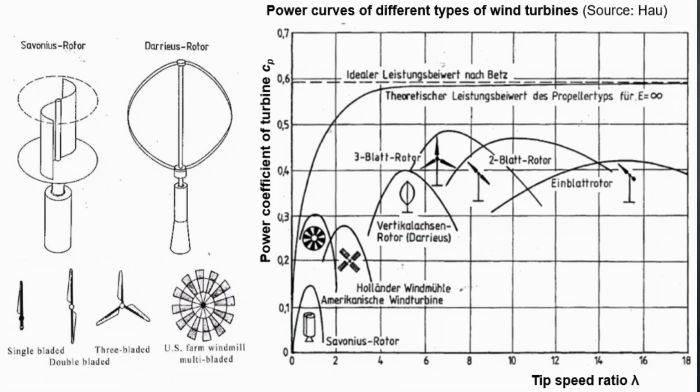Here, there's also a publication, German, so you see here the highest is the single blade rotor with a tip speed ratio, but you don't see those wind generators very often, or let's say extremely seldom, because the mechanical stress for such rotors is very high, and so maintenance and costs are quite high. In the 80s, there have been very often two-blade rotors, but at the end, the Danish design with a three-blade rotor and an average tip speed ratio lambda is almost exclusively used now because the lifetime is very long and the maximum conversion coefficient is quite good.